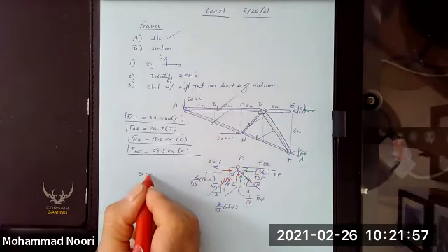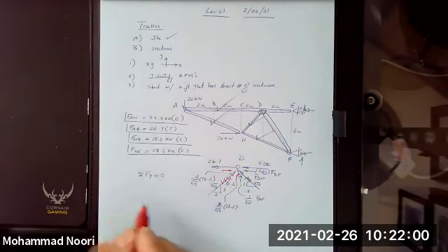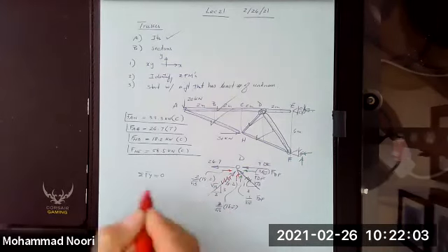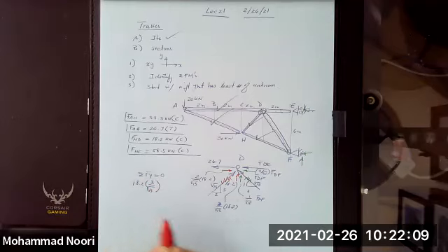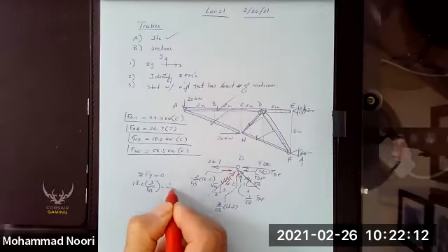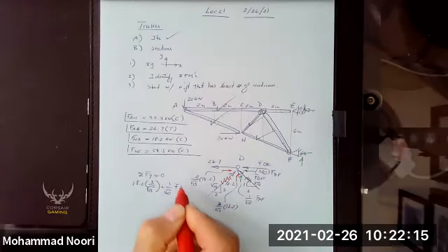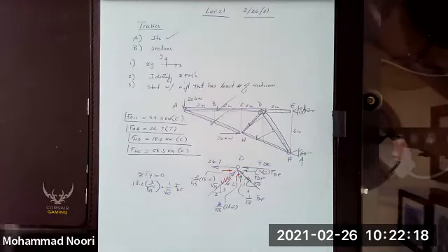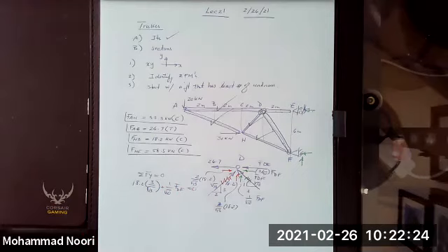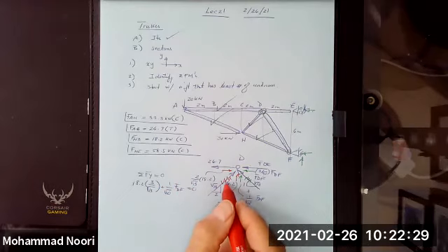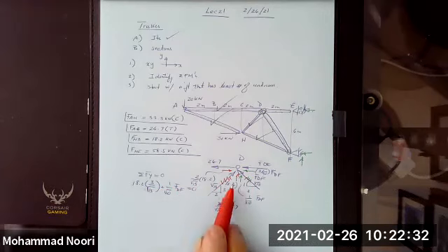start with summation of force along y equal to 0. So I have this one, 18.2 times 3 over square root 13 plus 1 over square root 10 times this unknown force F_DF, and that's it, is equal to 0. Oh, no, I'm sorry, I have this one too. I have this one, and I wrote both of them, right? So that's all I have.